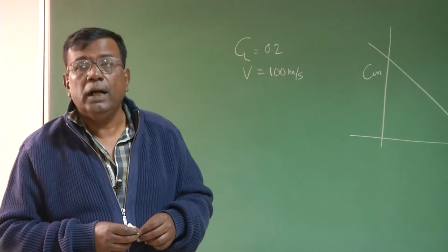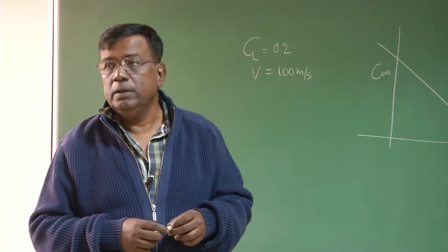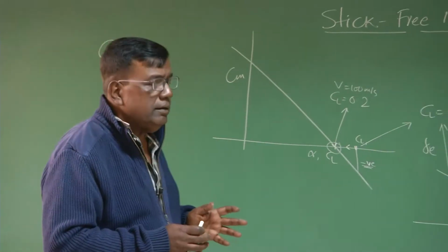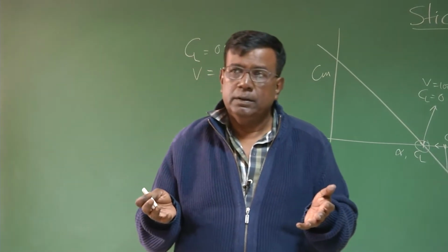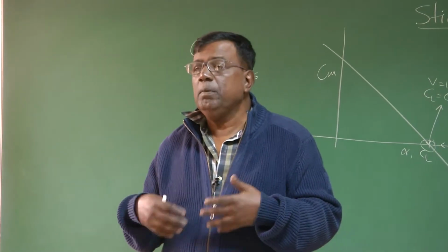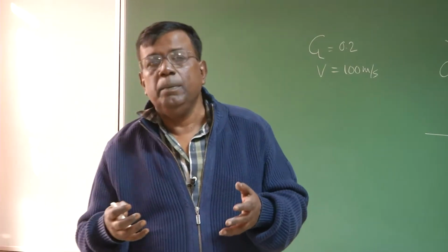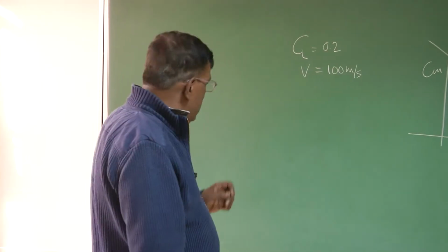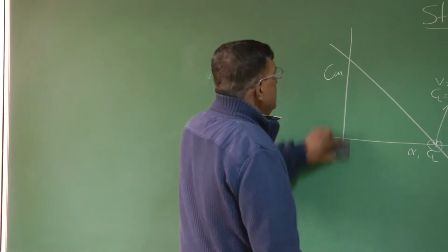And you need to use that concept of stick force to define a stick-free neutral point. But be very clear, if you see my module, the airplane has only one neutral point, right? It is the stick-free neutral point we are defining so as to develop a mathematical model which will help to give a feel for the pilot. That's all. Okay. So now the question is, we want to find out the stick-free neutral point through an experiment.